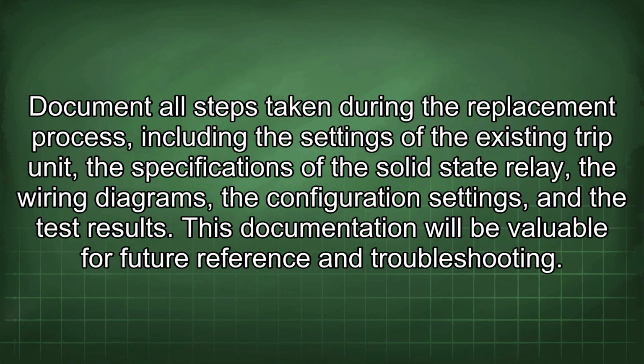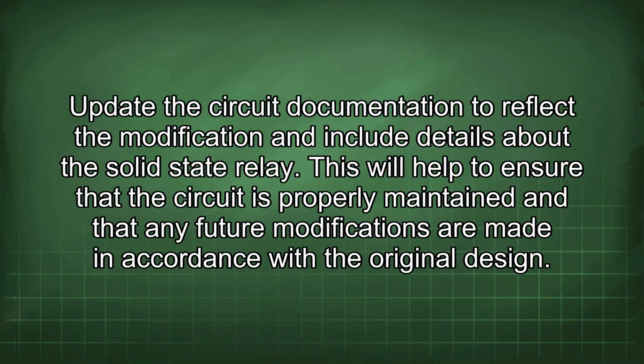Document all steps taken during the replacement process, including the settings of the existing trip unit, the specifications of the solid-state relay, the wiring diagrams, the configuration settings, and the test results. This documentation will be valuable for future reference and troubleshooting. Update the circuit documentation to reflect the modification and include details about the solid-state relay. This will help to ensure that the circuit is properly maintained and that any future modifications are made in accordance